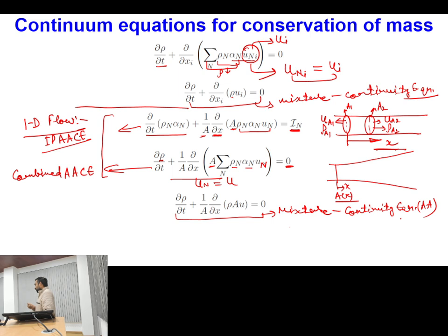Yes, we are taking only in one direction, okay. So this is complete derivative, because we are only talking about the area average thing, so in a simple operation. Whenever you are using the averaging of area, you are not interested in the distribution of individual phases in an area averaged quantity, okay. So within this area, in whatever arrangement phases are arranged, you have to do summation over the phases, not summation over the area.